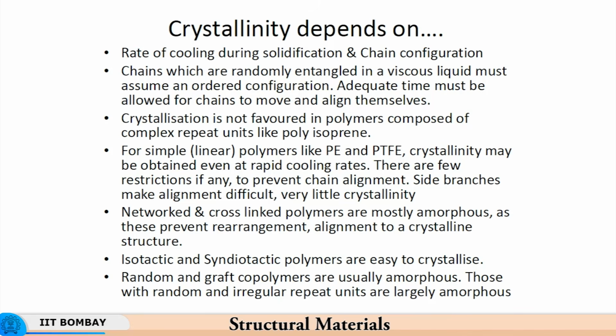to crystallize. On the other hand, atactic polymers will not have this symmetry, and due to lack of symmetry, the two polymer chains will be difficult to align, and therefore difficult to make an orderly arrangement of atoms. So that's why they will be difficult to crystallize.